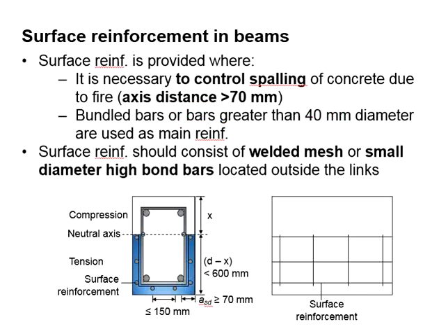That means the surface reinforcement for the beam in the question is also not an issue. The concrete cover is only 30 mm, not really thick, and the bar size provided is only 20 mm, not greater than 40 mm diameter. Therefore, the risk of spalling is not high. With that, you do not really need surface reinforcement.